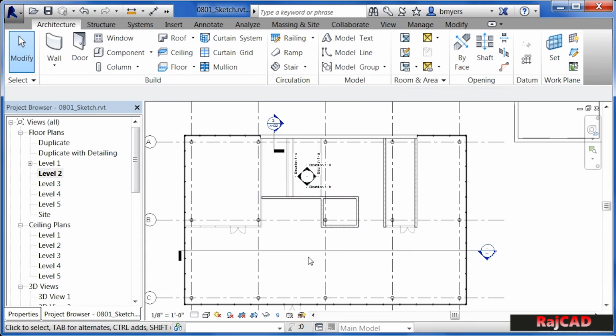These ones that are darker, they're coming up through the second floor and going up to some of the floors up above. Now we could always modify our floor so that it will have holes for each of these walls, or we can adjust the walls themselves so they'll just go up to the underneath side of the floor. We have a variety of different things that we could do.